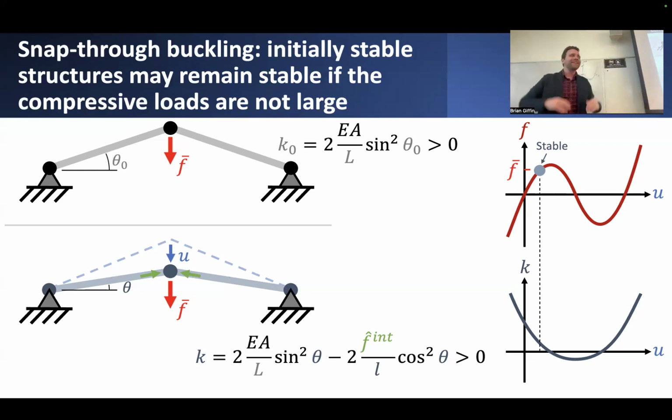And there'll be this competing or contributing effect of the tension stiffening. It'll continue to be in compression, and increasing compression will lead to continual loss of apparent transverse stiffness of this arch structure, until eventually you'll reach a critical point where, once you apply a critical load to it, the stiffness of this arch will become zero.